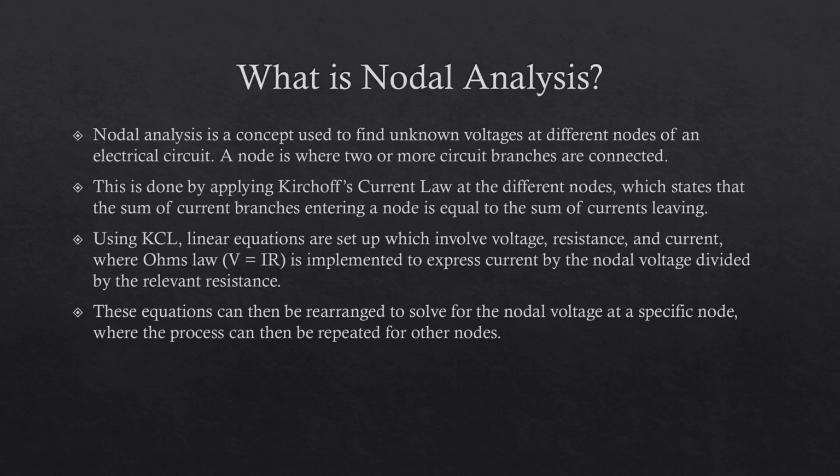Nodal analysis is a concept used to find unknown voltages at different nodes of an electrical circuit, a node being where two or more circuit branches are connected. This is done by applying Kirchhoff's current law at the different nodes, which states that the sum of currents entering a node is equal to the sum of currents leaving.